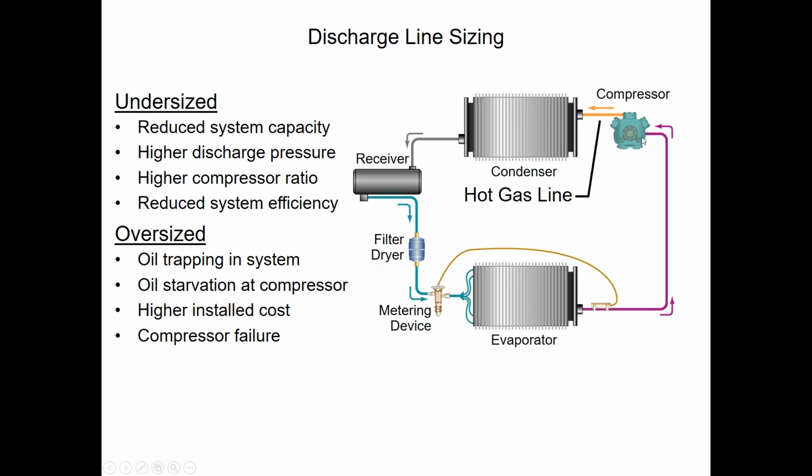Liquid is really good at entraining. Its miscibility with oil is fantastic, and it just washes all the oil out of the compressor and carries it out. And then if your pipes aren't sized right, or you've got some issue going on, then we can't get that oil back to the compressor. And then what people do is, oh, I'm low on oil, they add more oil. Well, then that oil leaves, and it's this endless circle that ends up in disaster by compressor failure.